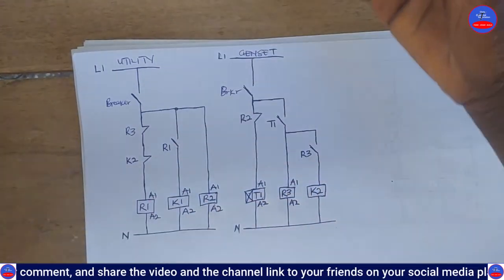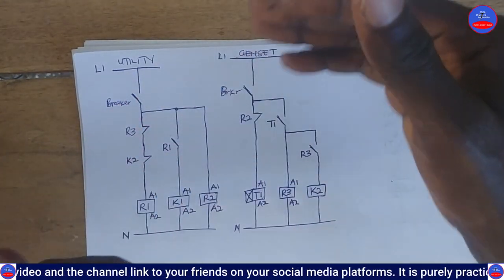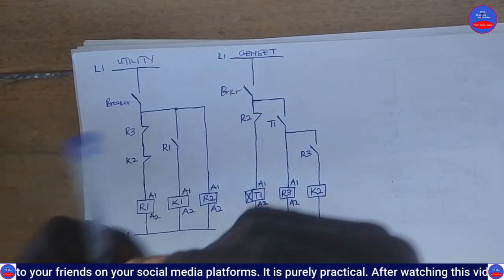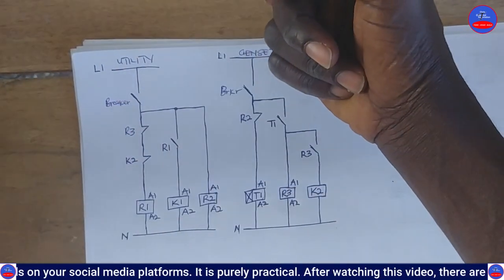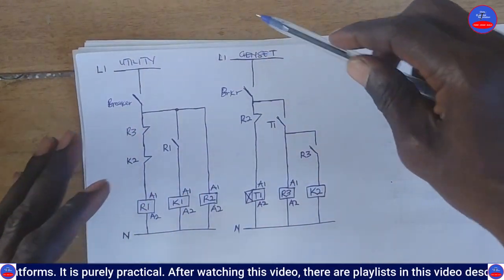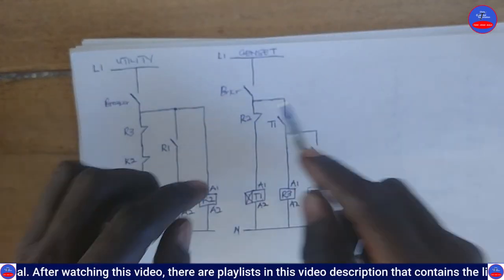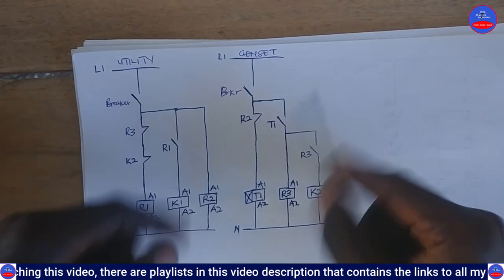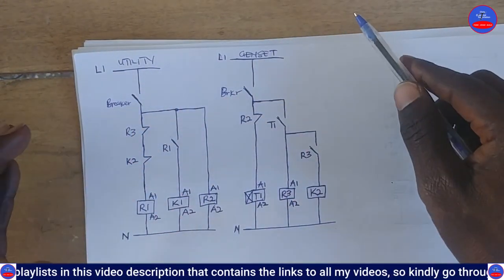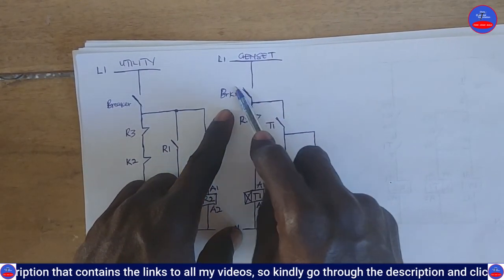When the generator has started, some generators have some on delay. After the generator has started, the output will not switch on. It will delay for some time before the output switches on. So let's assume that our generator has started. After the preset time, the on time, the output will switch on by closing this breaker. We are using this one for the demonstration.